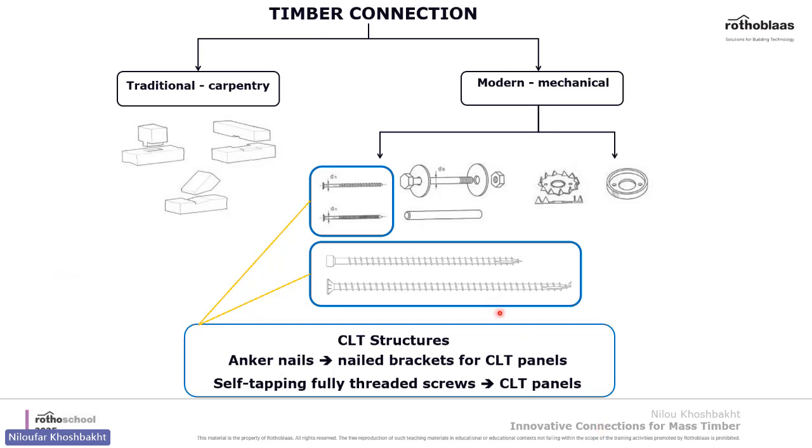And yeah, they have been around for many years, but along the way, especially for CLT structures, they've been optimized, and still we use nails. We use nails with modern brackets, for CLT plates, and also we use self-tapping fully threaded screws for connecting CLT panels together.